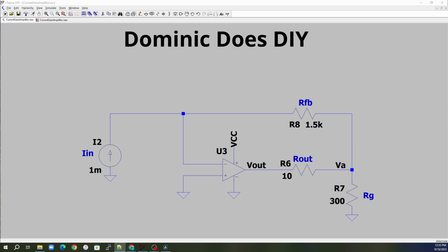First thing, we might just think to bias the op-amp to try and elevate the system. If we just try and bias with, say, 2.5 volts, the system does not gain like we expect. It is because the op-amp will no longer sink current but source it. So we lose the gain feature of this circuit because instead of our output current being equal to the feedback current plus the ground resistor current, we have our ground resistor current equaling the feedback current plus the current that our op amp is going to supply. So this won't work for us in this system.